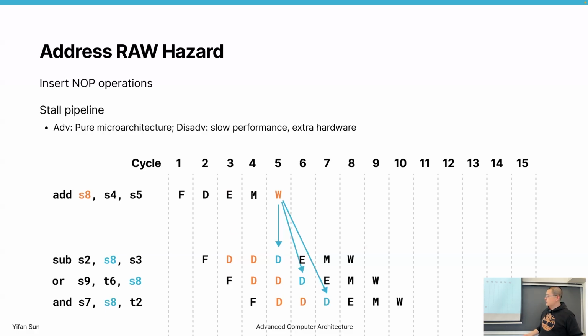As you can see, starting from this type of design, the design is getting really complex, and the CPU is spending a lot of die size and energy on determining the right execution path, so that it can limit the size that's really for the ALU, the unit that can do the calculation. So GPU is going towards the other direction.